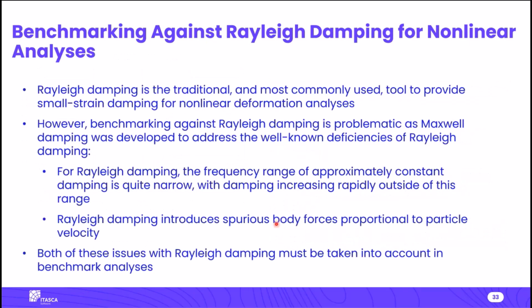All right, so the next validation verification problem we looked at is benchmarking against Rayleigh damping for nonlinear analyses. So again, Rayleigh damping, that's the most traditional, most commonly used tool to provide small strain damping for nonlinear deformation analyses.